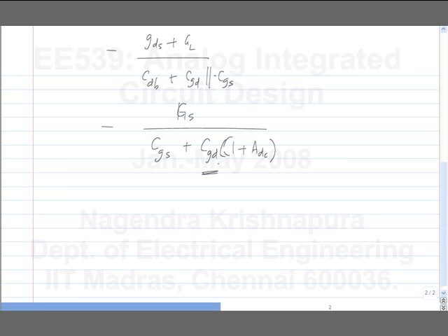Is this correct? What do you think? Now, the idea in both cases is you look at the conductance, in this case it's GS, look at the capacitance across it, which turns out to be CGS, which is directly across, plus Miller multiplied CGD. And then here you look at the conductance at the output, which is GDS plus GL, and the capacitance across it, which is this. So, is the answer correct?